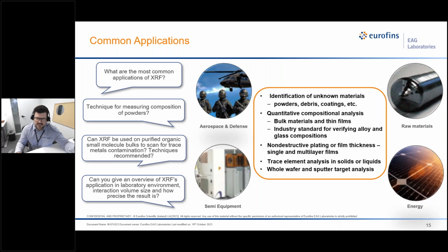Since solid samples, powders, and liquids can all be analyzed with XRF, some common applications include the identification of unknown materials such as powders, debris, and coatings, as well as quantitative compositional analysis of bulk materials and thin films. It is also considered an industry standard for both single and multi-layer films. Trace element analysis in solid and liquid samples is also commonly done, and we have the ability to do whole wafer and sputter target analysis.